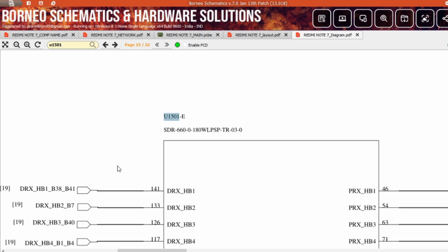When a phone comes to you, don't look at the model, which model or which company's phone has come to repair. I always say, when a phone comes to you, don't look at the company or model name, right? If you do not have schematics, you can repair with the IC number, which IC, power IC or your chipset master IC is installed.